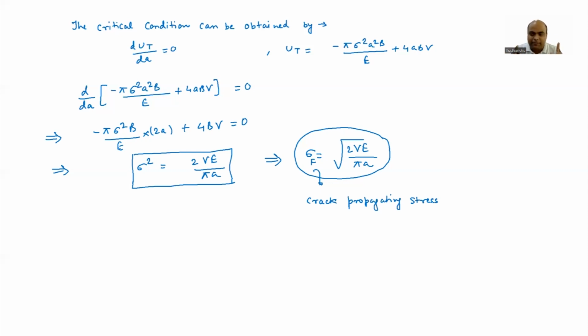If you remember, we discussed the relationship between the crack length and stress concentration, isn't it? So if the crack length is higher, stress concentration is going to be higher at the crack tip. This means that the required stress for fracture is going to be lower, and that is what this criterion is proposing also, isn't it? So it's a very nice relationship between the crack length and the fracture stress. And we can correlate this with the stress concentration concept we have already discussed before. Okay.